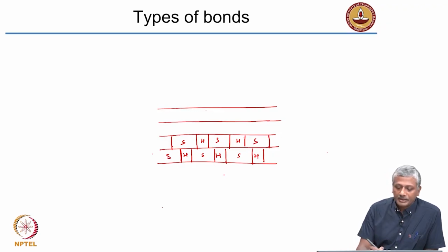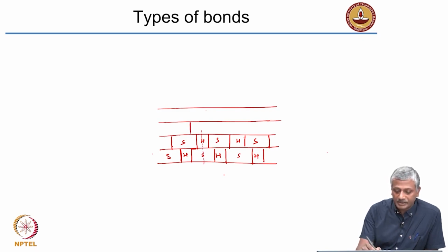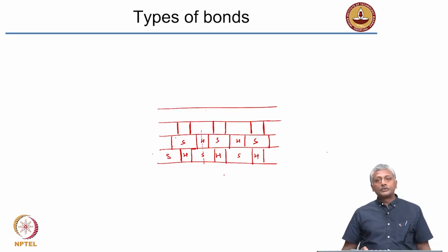Okay. So again I am satisfying the rules of minimum 5 centimeters overlap. I am also satisfying the rule that the center line of the header coincides with the center line of the stretcher below it and also above it. So next layer will again be a repeat of the same layer. Okay. So this gives a very nice pleasing aesthetic appearance.